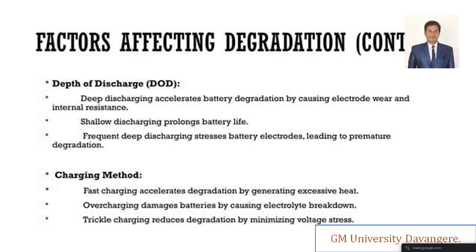So we have to monitor the temperature in the state of charge. We have to monitor the voltage. We have to monitor the current. These are the three major parameters in the charging methods. If you fail to do this, obviously the degradation will happen. If you don't maintain the temperature and the voltage, that is what I told you.